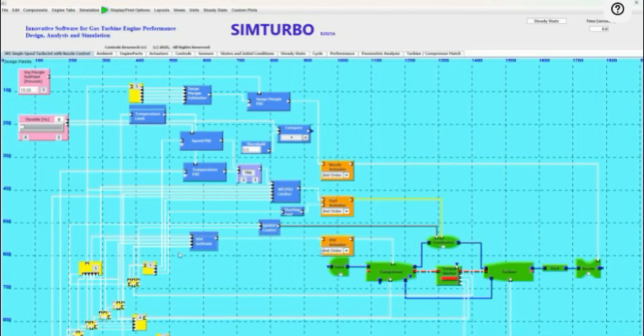In addition to the sensors are the other yellow components of groupers and parsers, which properly collect and disperse the sensor signals to the control. The surge margin set point and pilot throttle command are input into the PID controls. These set points are represented in pink.